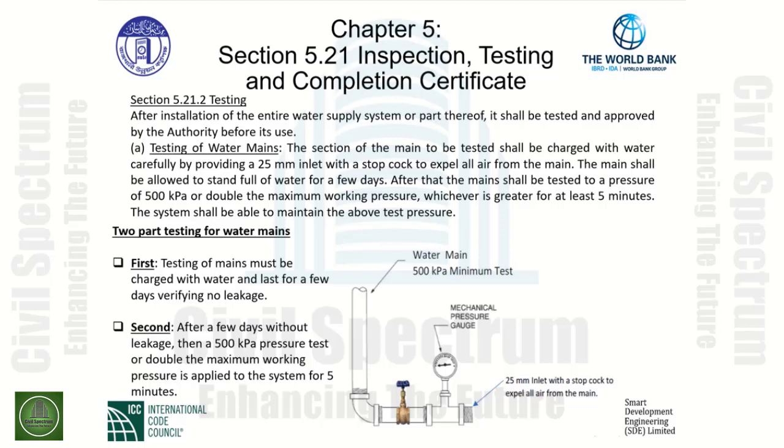After the mains have been set for a few days, then they need to be tested to a pressure of 500 kilopascals or double the maximum working pressure, whichever is greater, for at least 5 minutes. The system shall be able to maintain the above test pressure.